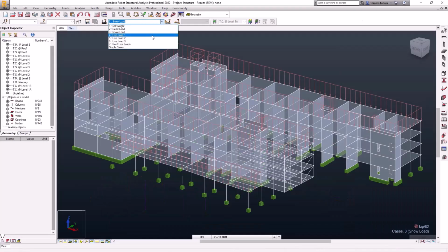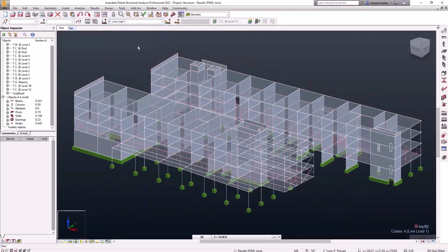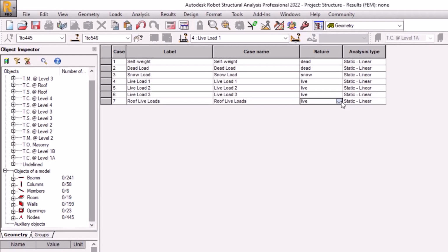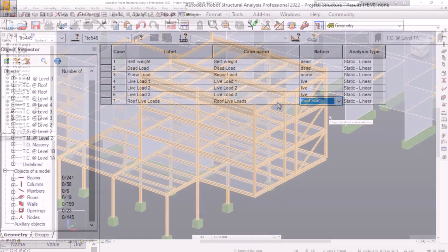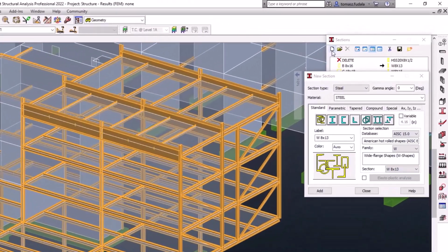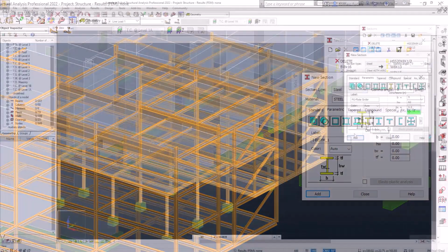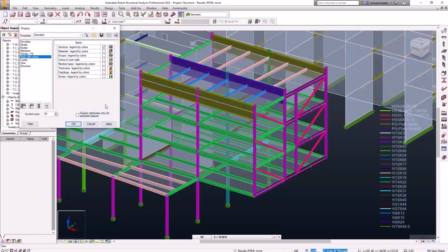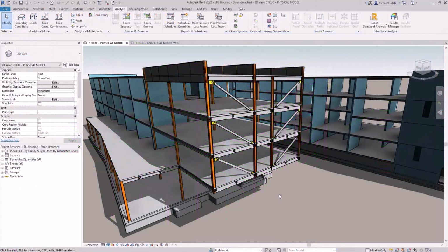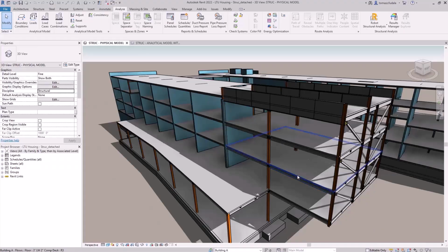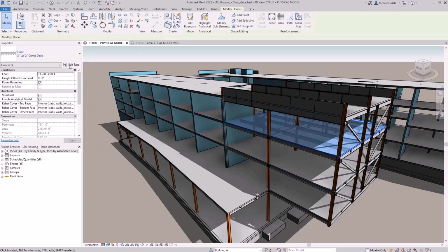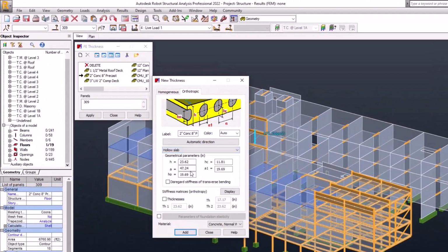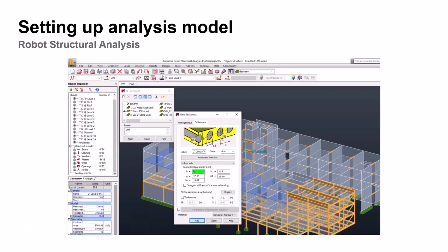And after transferring the analytical model from Revit to Robot, the engineer must review and adjust model parameters, cross-sections, slab types, and local coordinate systems before analysis, of course. The display dialogs help toggle nodes, loads, supports, and finite element mesh for verification, while tables allow quick parameter adjustments. So engineers can redefine temporary sections, set correct thickness, and align orthotropy direction, ensuring the Robot model accurately reflects the design intent, of course.